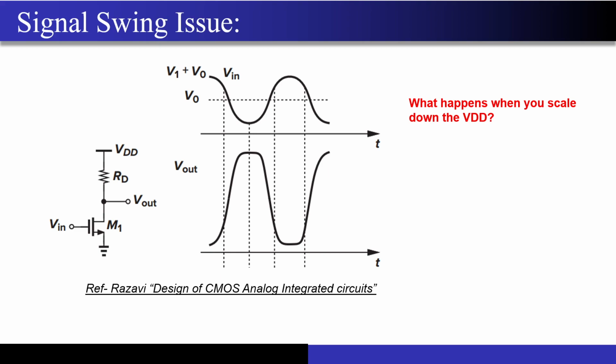Correct. So my question was, in analog design in general, it's all about trade-offs, right? In one way there's a trade-off in some other thing. When you try to increase the gain, maybe you compromise swing limits, depending on your circuit. So there must be some trade-off in going to a higher channel length. Let's say I want a long channel device. Using the common source amplifier example that you had given, you talked about the output impedance. If I keep increasing channel length, what would be the trade-off there?